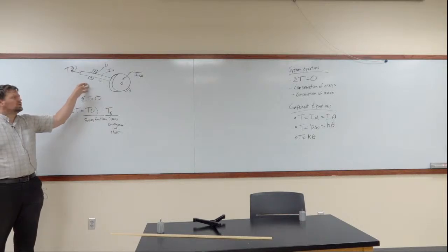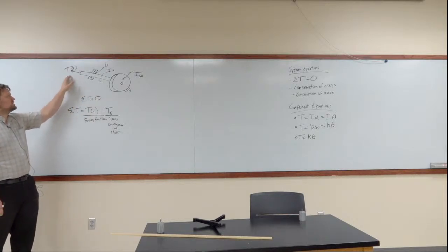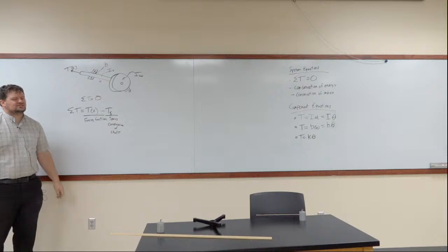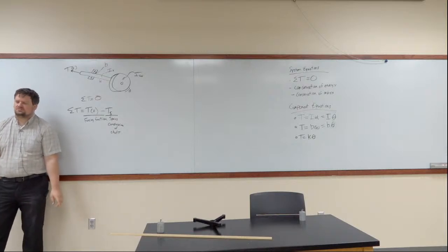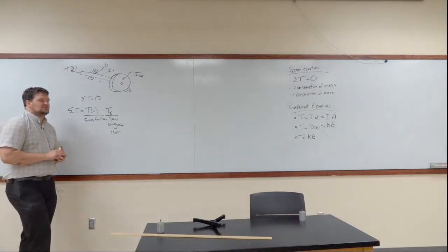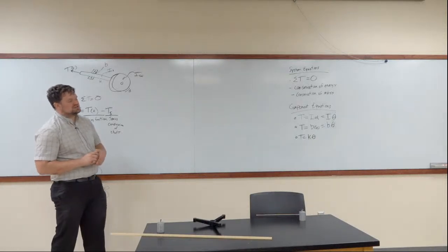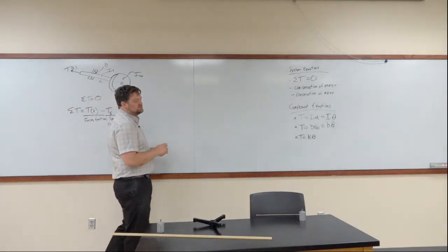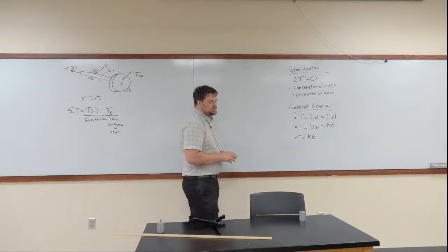Well, the forcing function is causing the torque over here. But what is creating the torque in the bearing? Anybody know? It's not the normal force. That one is not creating a torque because it acts perpendicular to the shaft. There's no torque associated with that. The cross product between the distance from that force and the force itself becomes zero.